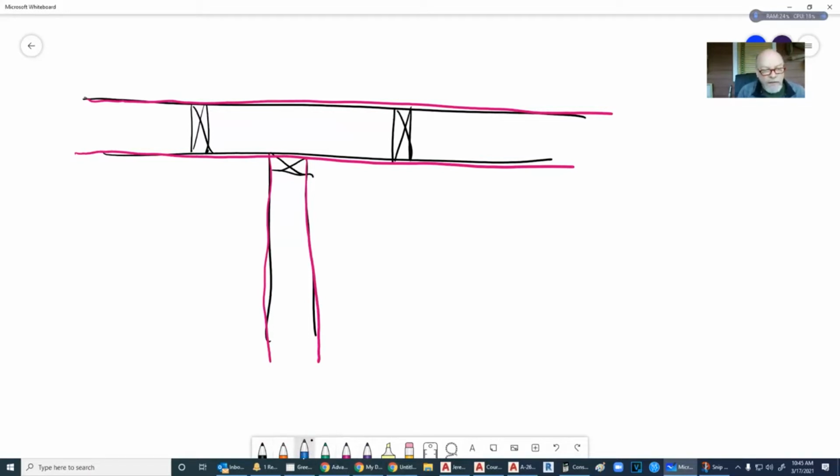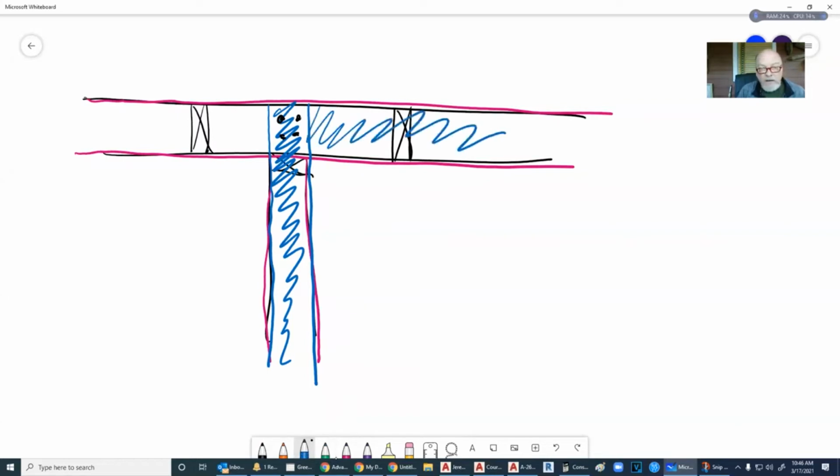This double top plate is going to go on top of the through wall. In other words, this is going to run across the through wall, and we're going to tie this in with a couple of nails here so that the top of this doesn't move. Then this other one that we're going to put up just takes up the space. If we were lined up with our rafters on that, technically we wouldn't need that double top plate, only to tie in this wall here. So this is really crucial.